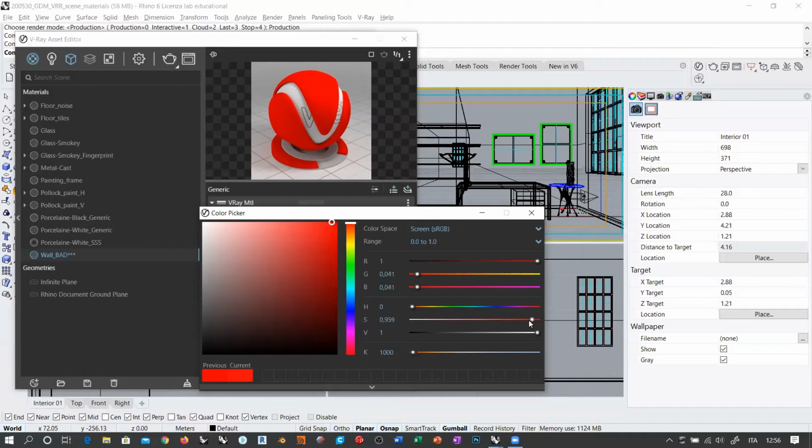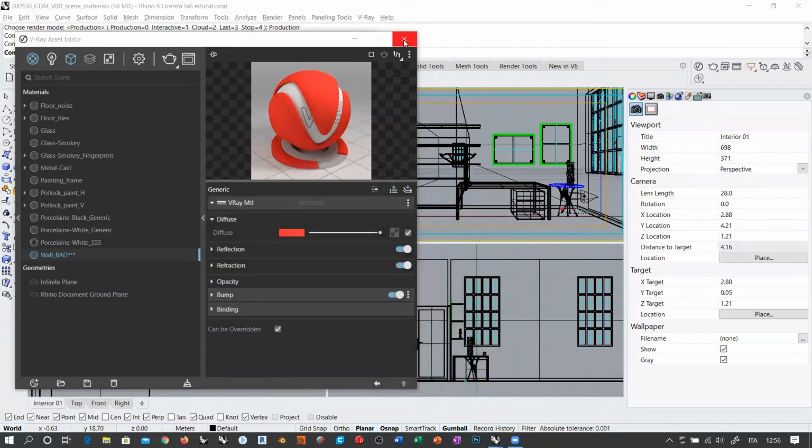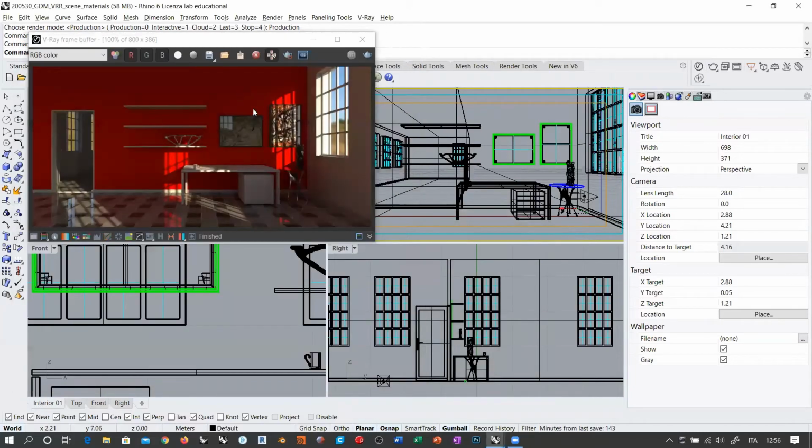So you can go here and desaturate it a little. You see, so it becomes a little more dull, as a color. But this desaturation makes it less powerful during the rendering. Okay, so I'm going to exaggerate once again, but I want you to take a look at the result in this area. So let's render this.